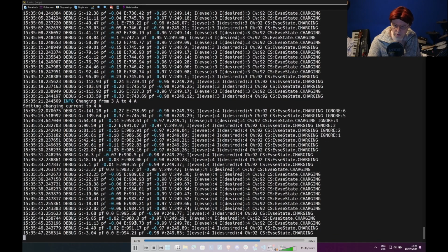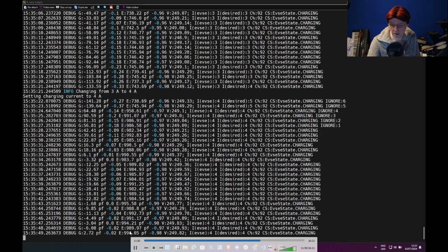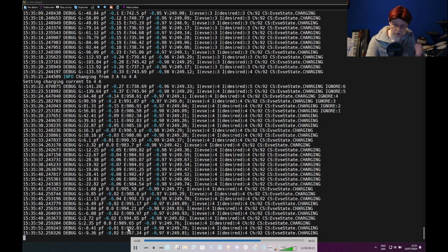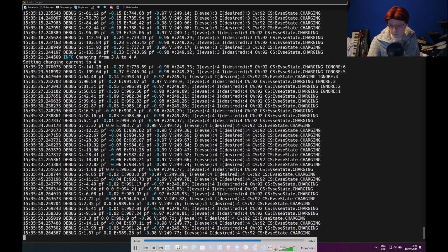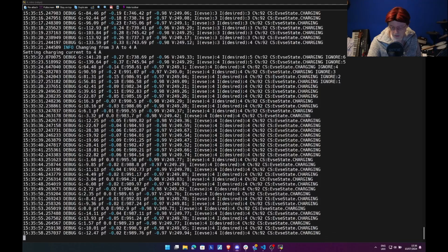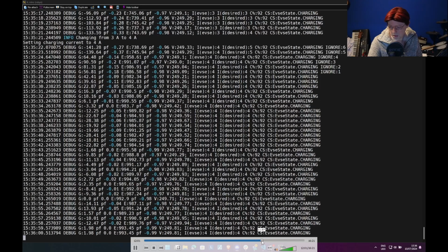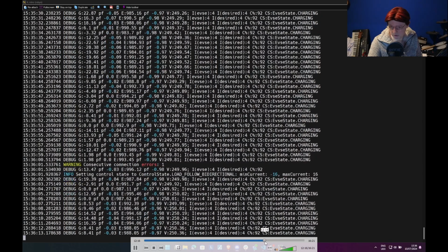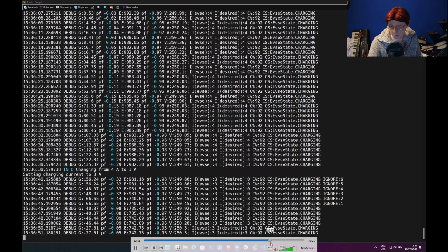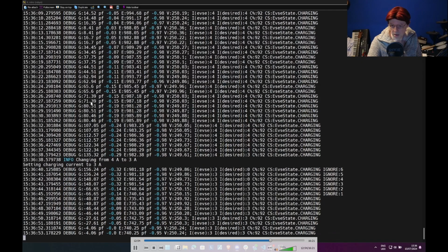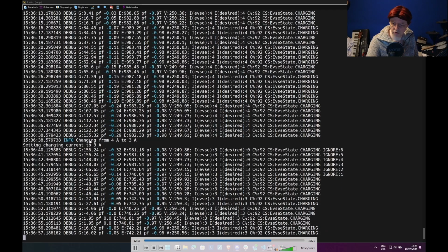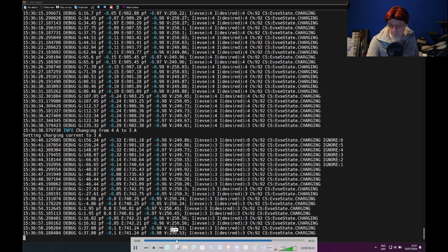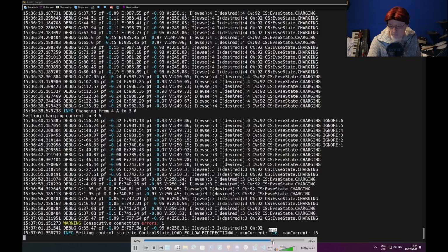And we can see that the wallbox is actually taking around 1000 watts here. At 4 amps, 249 volts, that's about right. Is there anything else of interest in this one? I think it maintained at 4 amps for a while. Now then, the grid was powering the charging sufficiently that it went back down to 3 amps. So that all works quite well.